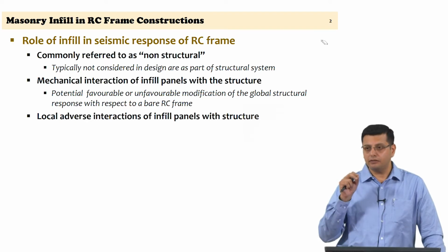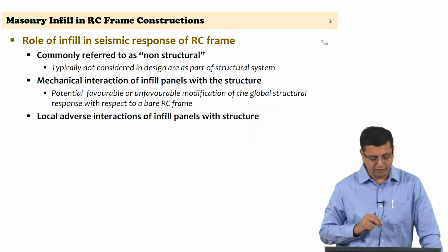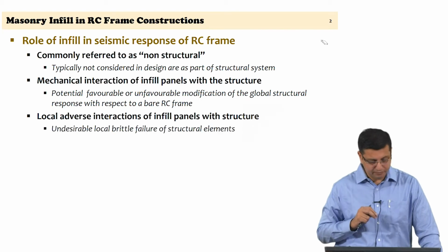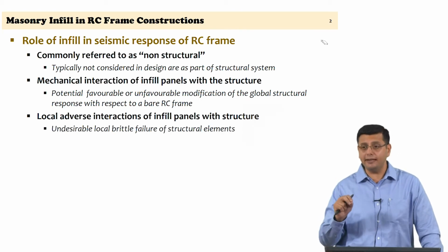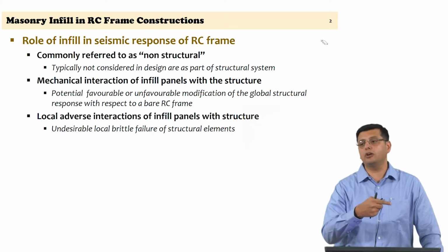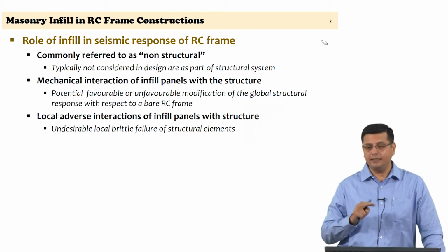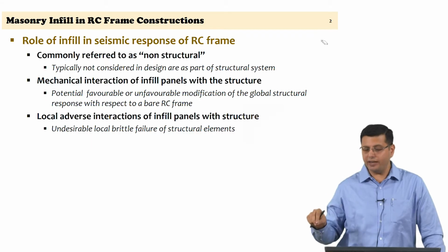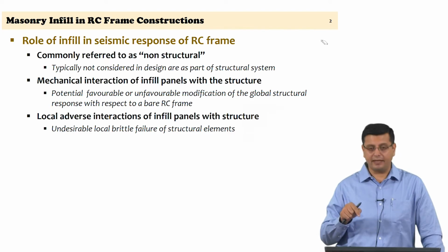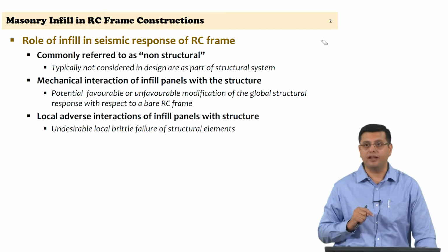You can have, because of the interaction of the infill panel with the reinforced concrete frame, local effects as well, local adverse effects of the interaction which can cause not only localized damage in the panel, but also localized damage in the frame, which is the lateral load resisting element. So, that interaction causing local effects in the panel can have a repercussion on brittle failure mechanisms in the lateral load resisting elements of the reinforced concrete frame itself.